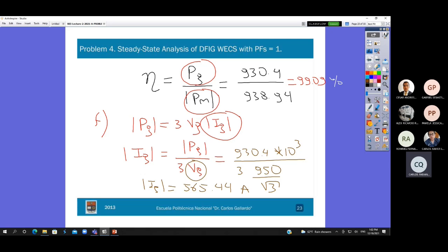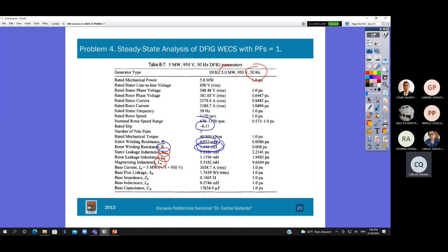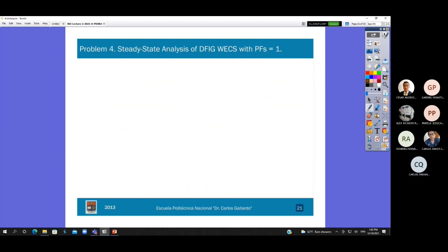So in the beginning, I said I have two methodologies in order to compute the mechanical torque and the mechanical power. Do you remember my first methodology is using the equation proportional to the square, right? So we have already used this formula: the mechanical torque for the new speed is equal to the rated mechanical torque times this speed ratio.